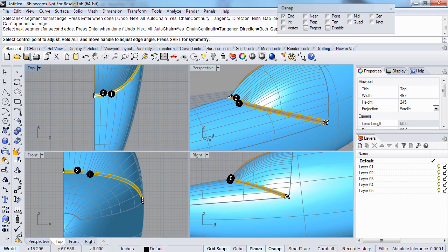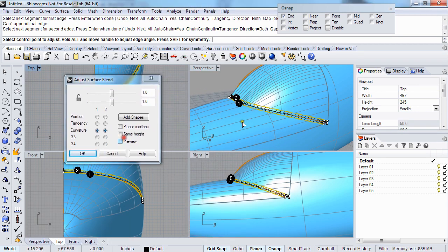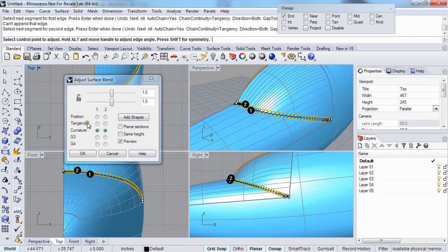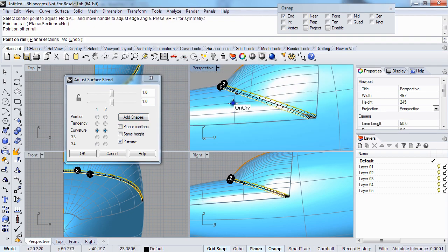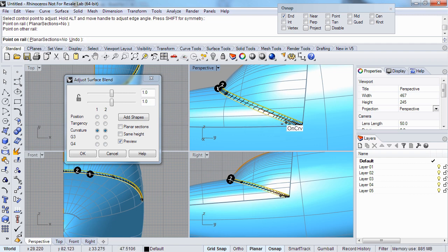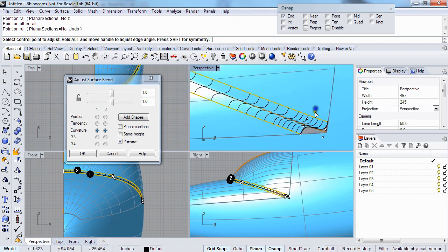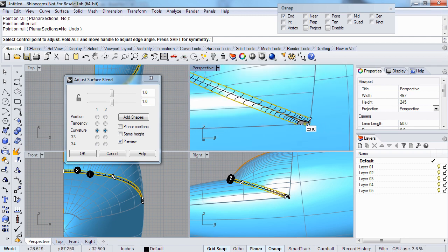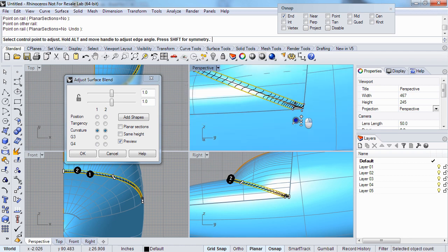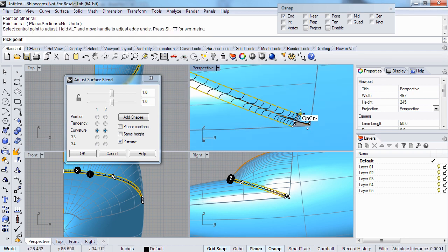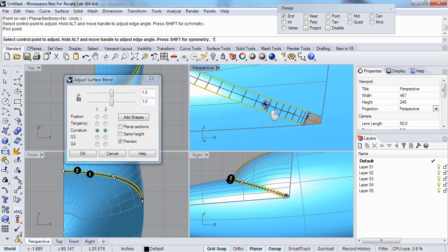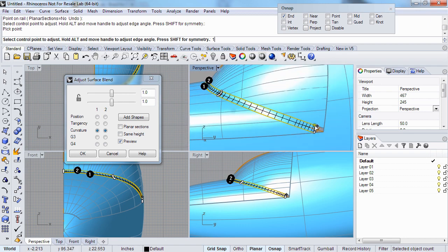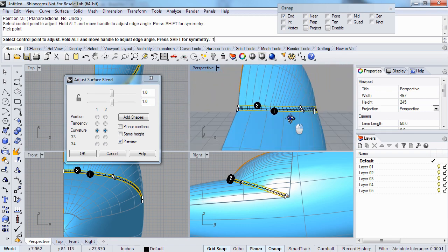Here, and let's move for here. Preview here. Of course, there are a lot of cool options in the blend surface command. The level 2 training talks about that quite a bit. And I'm going to go add some knots there. And then what I'm going to do here is, now we still have this strange little corner here. So what I'm going to do to solve that is take the end point of my blend and move it so that we get a nice clean surface here. I have to reset the blend bulge values after you move that to stop the surface from folding over on itself.